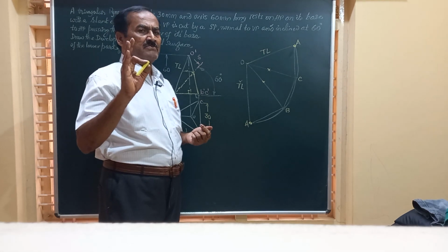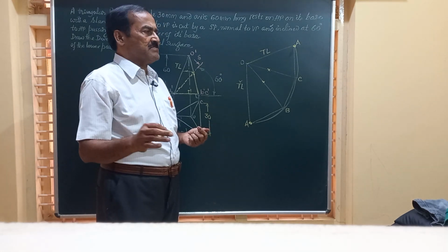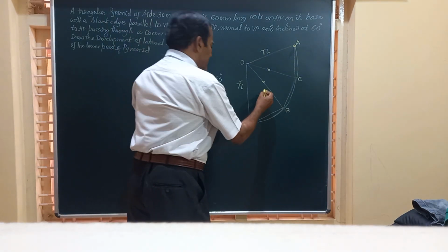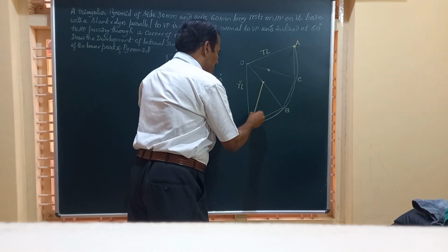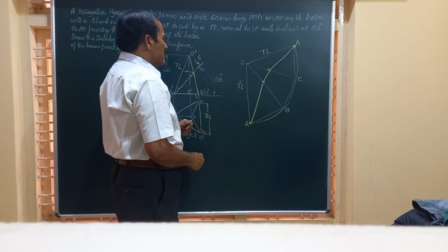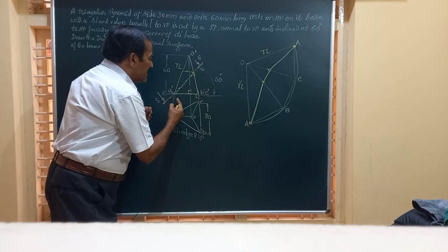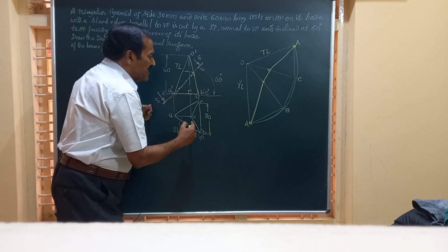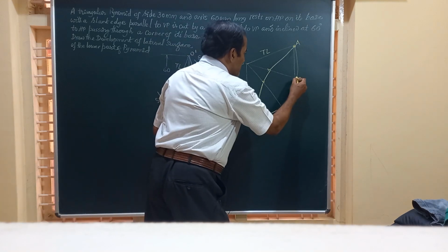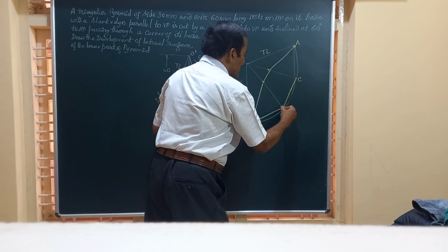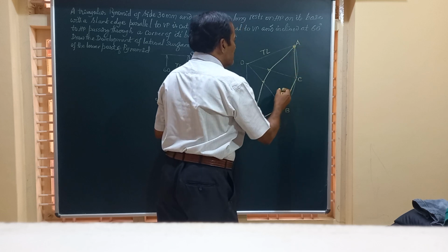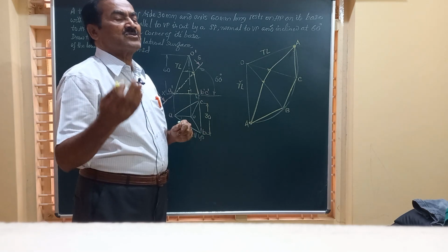Friends, for all these pyramids, cubes and prisms, whatever the points you have got here have to be joined by straight lines. So friends, I am going to join like this from these two and again from here. And friends, you can find here the complete base of the solid, that is edges AB, BC and CA are to be shown by dark line. So this is AB, next comes BC, after that comes CA. So we have to show all this by dark line, because for all these pyramids, the base will have straight edges.